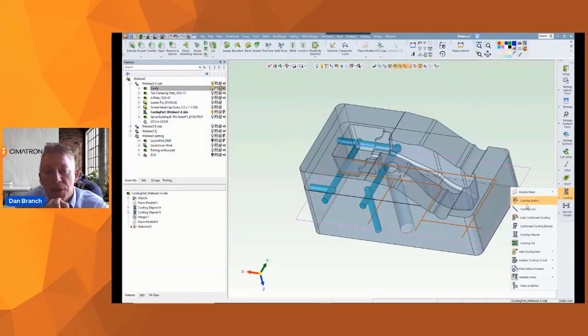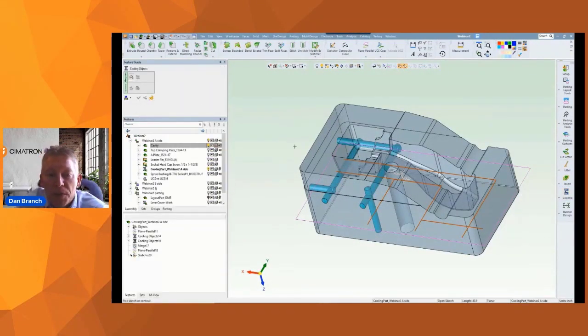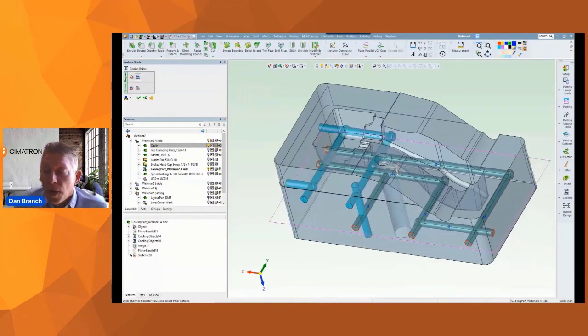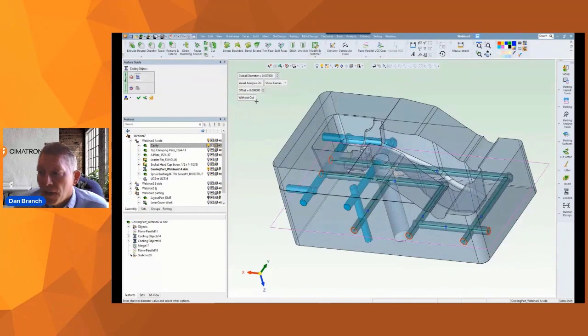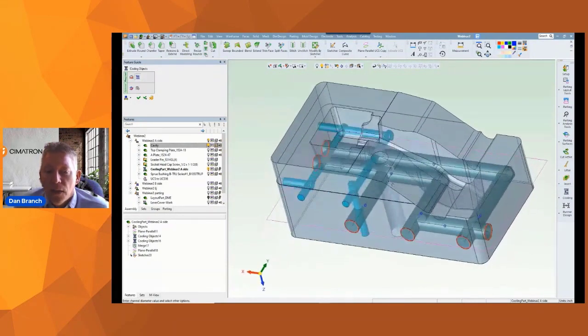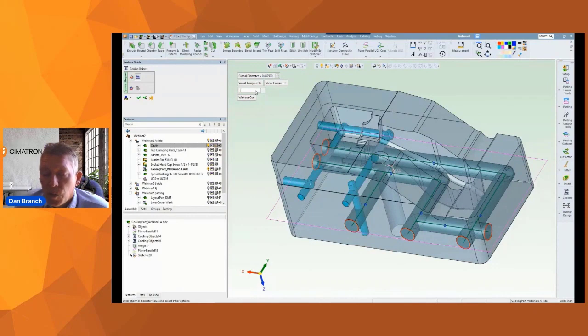So a cooling object function then is going to create the pipes that follow this sketch. And it has several options like the channel size or the drill overlap. And another cool thing you can do is a quick analysis for any water collision issues. That works by intersecting the cooling lines with the cavity geometry. In red here, I'm being shown where the lines break out of the block, and hopefully nothing else. But I might see some more once I apply an offset to the lines. This adds a safety distance on top of the channel diameter and again checks for problems.